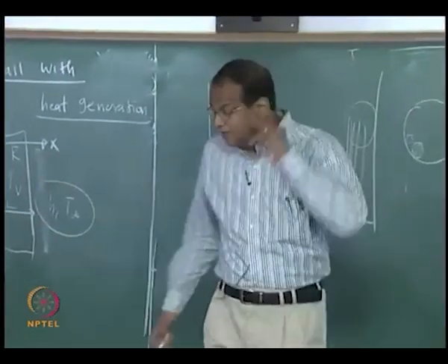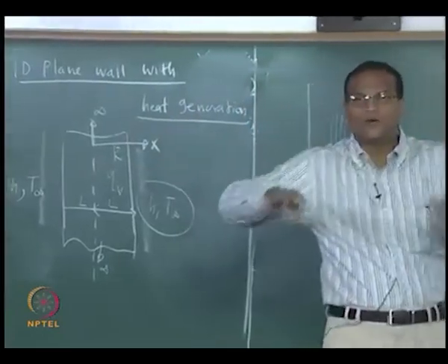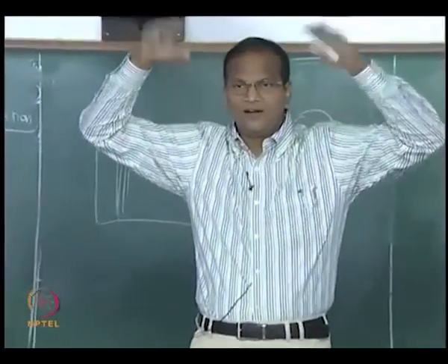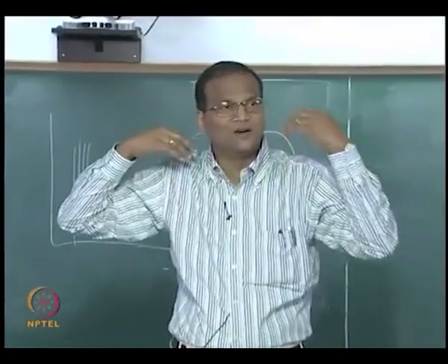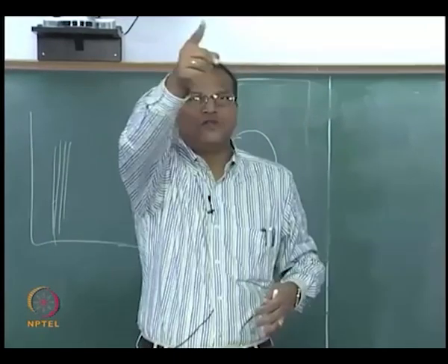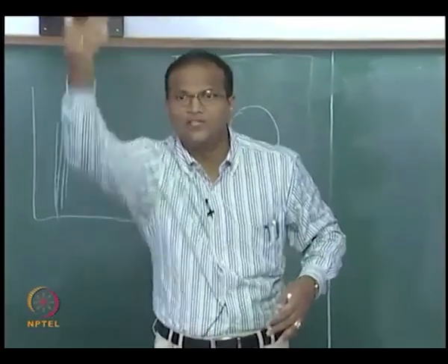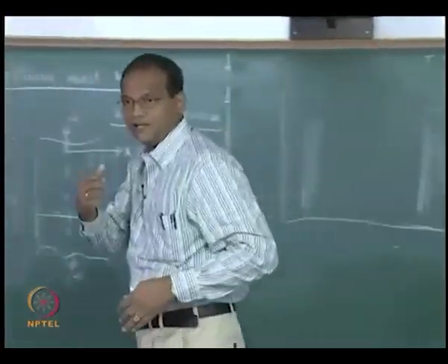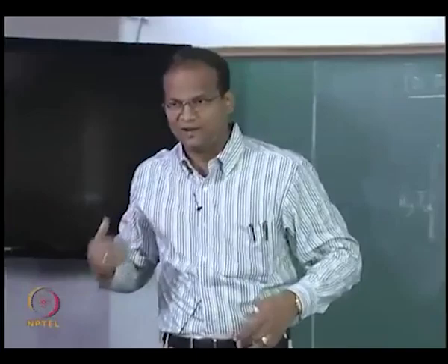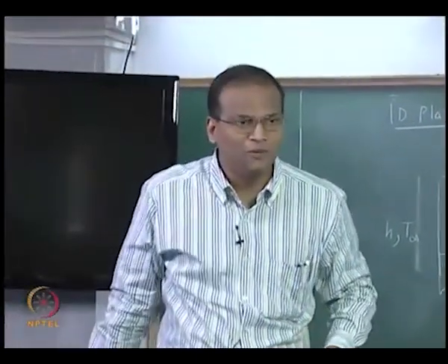Immediately after a station blackout, there will be operators who will ensure that control rods are lifted so that the reactor goes to subcritical conditions. But it is not like switching off a light; nuclear reaction has a half life, it will continue to generate heat for the next 24 to 48 hours. It may not be at critical conditions, but at a reduced power fission heat will continue to be generated.